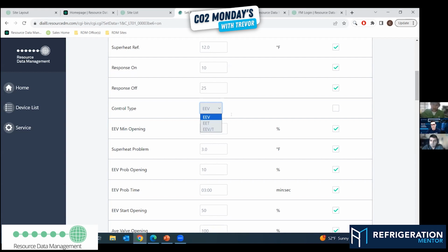Well, if your temperature in that case is reading 25 degrees or 30 or 50 degrees, it's going to make that valve wide open until it gets down to, it's basically a chart inside the controller is what I've kind of figured out, rate of time versus change and so on and so forth. And until it gets in that bubble again, it's not going to revert back to superheat. It just won't. So you get floodback instances, and then you get frosting going on, and you just get a lot of things going on. So that's a real important setting on these case controllers.